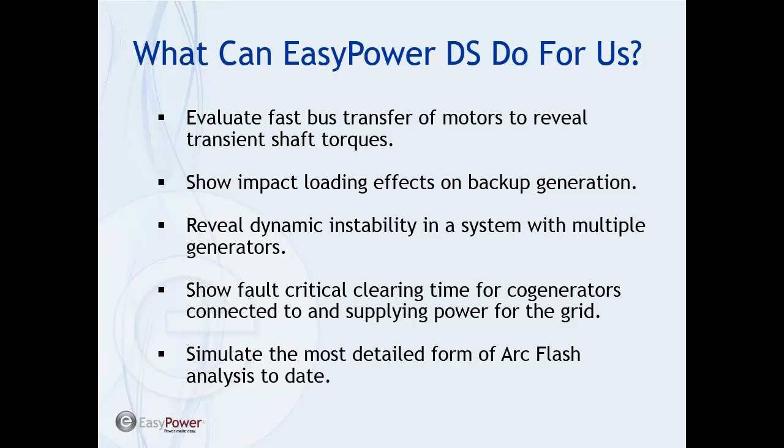I'm sure from school and some of your background knowledge, there was that case we automatically had put in front of us, which is you had two generators with an inductance in between them, or a reactance, because we were looking at things at some system frequency like 60 hertz. And we could evaluate when we would go dynamically unstable, where we couldn't keep stability. We didn't have enough synchronizing power between the two generators.